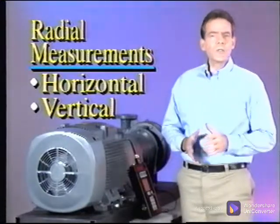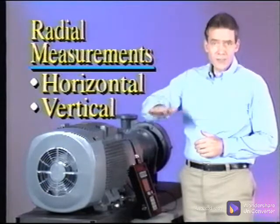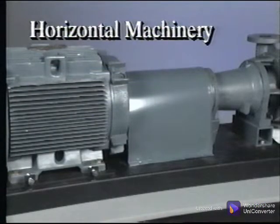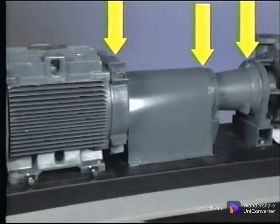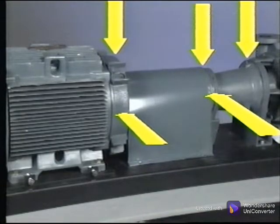These radial readings will give the analyst an idea of how the machine is moving up and down as well as side to side. For horizontal machinery such as this, where the mounting is at the bottom, we typically would expect less movement up and down because it is limited by the mounting. The analyst compares these vertical readings to the horizontal readings to check for problems, such as a soft foot condition or loose mounts.